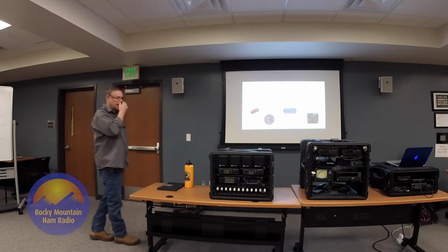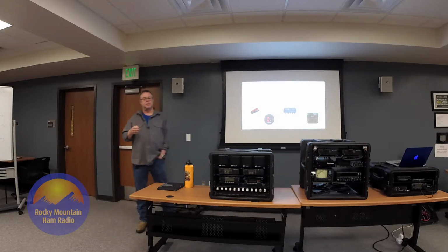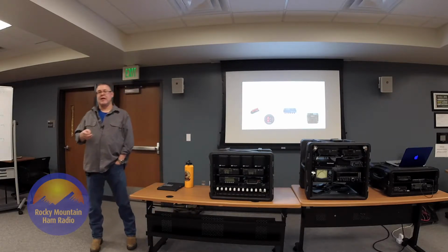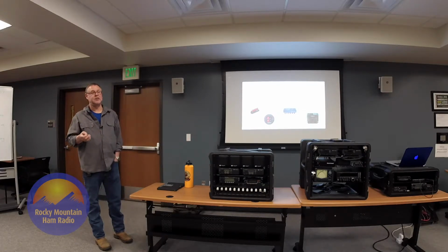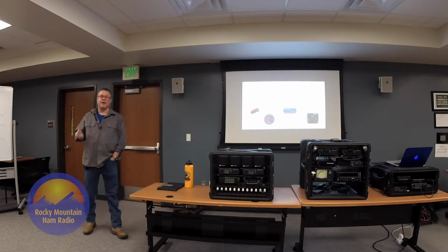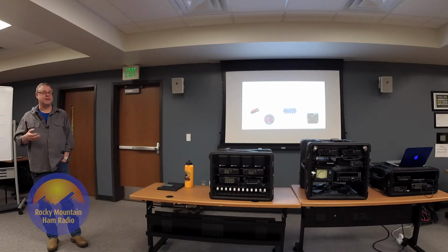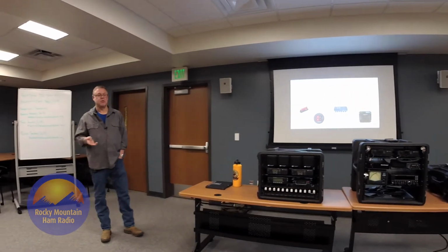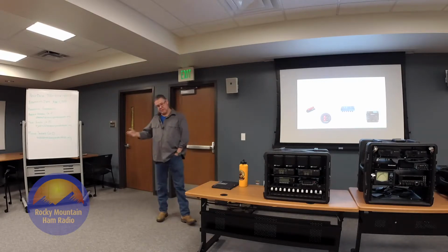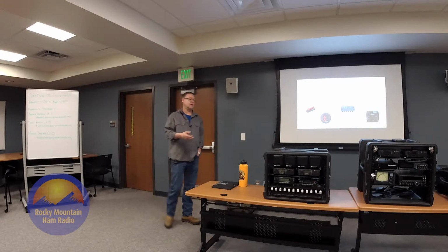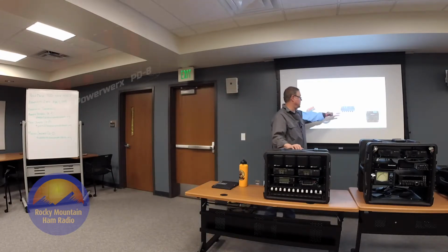If you don't design your box internally with Powerpoles, at least have a jumper or an interface cable that you carry in your kit so you can interface into someone that does. Because I can guarantee you if Arapahoe County shows up, Douglas County, Jeffco, Boulder, anybody shows up on some kind of event, they will have Powerpoles, and their power sources will have Powerpoles. If they have backup batteries that sit on the floor, they will hook in through Powerpoles. I'll guarantee it.